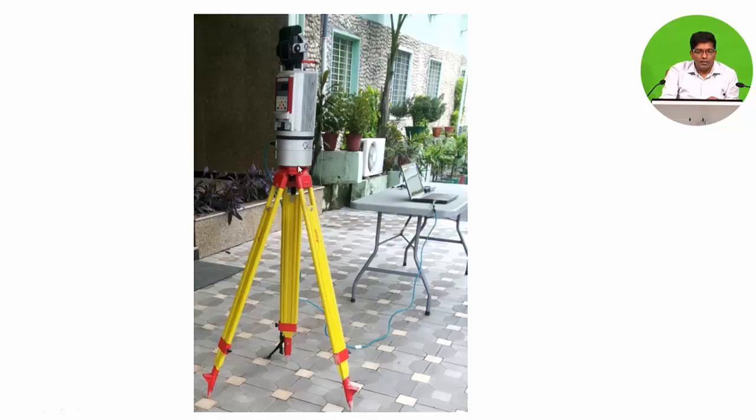And these TLS are normally equipped with a camera, so you can mount a camera, and on the camera you can also place the GPS so that we can georeference the data that we obtain from the TLS. And this TLS can be connected with a laptop so that we can do the operations on the TLS. The various operations that we do on the TLS are, firstly, we define how much area we want to collect, and within this area we have to give how much increment we want for the horizontal and also for the vertical. Accordingly the data will be collected.